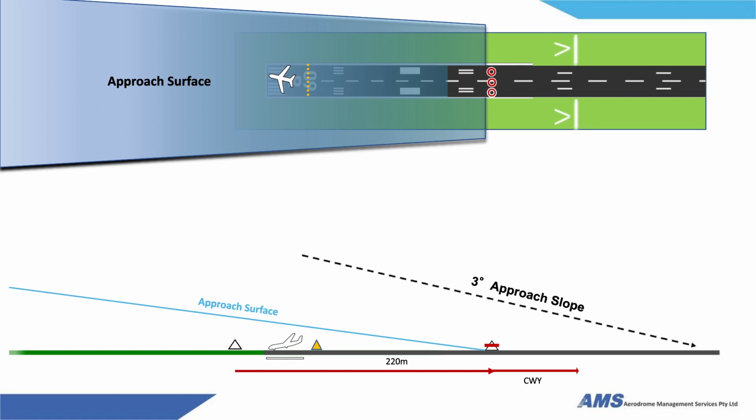This is a different scenario because we now have an unserviceable portion on the runway. We're still using our V-bar markers to identify the new threshold, but we now have to place unserviceability markers. Those unserviceability markers are identifying the edge of the new clearway, and being that we may have workers or mechanics to try and rectify the disabled aircraft, we've also placed out works limit markers.